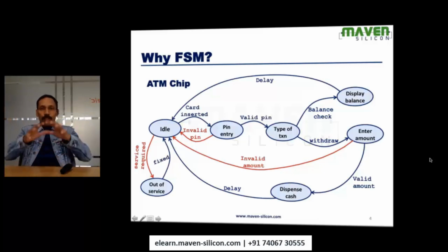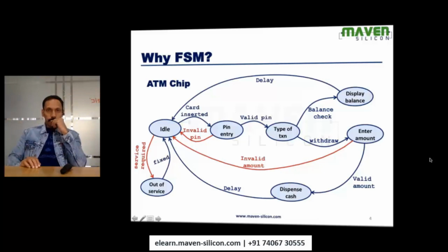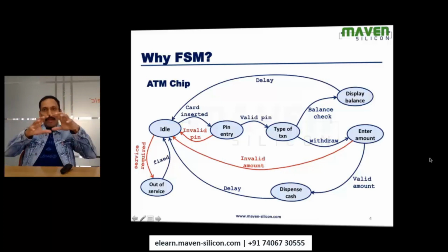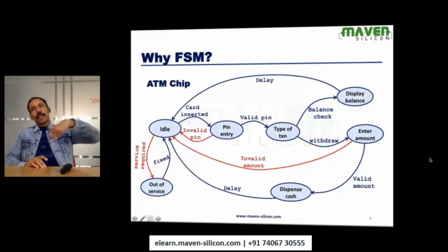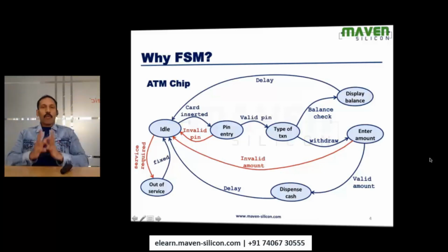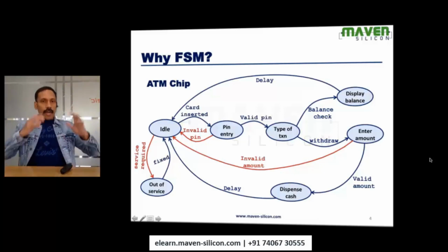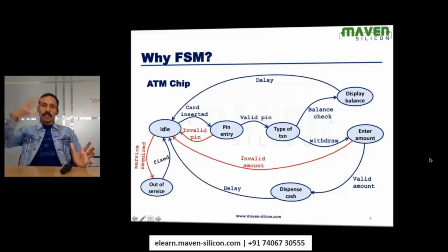But in reality, we don't do all these things manually. That's what you need to understand. In industry, what we actually do is define this FSM and straight away write source code based on this FSM using Verilog or VHDL. This is what I'm going to teach during the Verilog programming class: how to define a finite state machine in HDL. Once you understand this coding style, then you would be able to define any kind of FSM easily in Verilog.